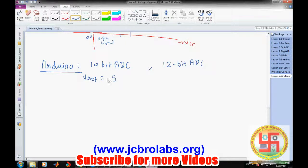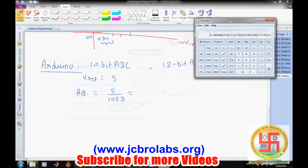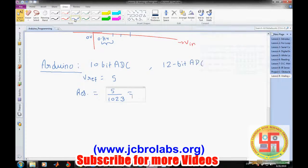So if V reference is 5, then the resolution or the step size will be 5 divided by 1023, and it is pretty good. It is near about 0.005 volt, or we can say 5 millivolt. So we can easily say the resolution of this ADC is 5 millivolt, that means if there is a change in the analog voltage within this 5 millivolt, then our ADC will not be able to detect it.